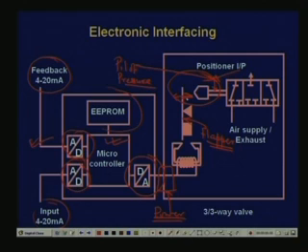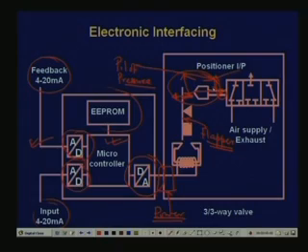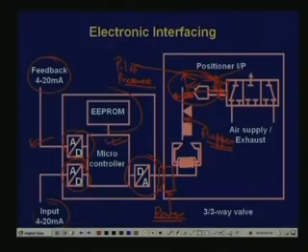Now, by changing the position of the nozzle, if the nozzle is very far away, then this pilot pressure is going to drop out and go to the atmosphere right here at the nozzle. Therefore, the pressure which will develop here is somewhere in between: here you have exhaust pressure, here you have pilot pressure. Now, as you bring this closer and closer, here you have the nozzle, so you are bringing the flapper closer and closer.